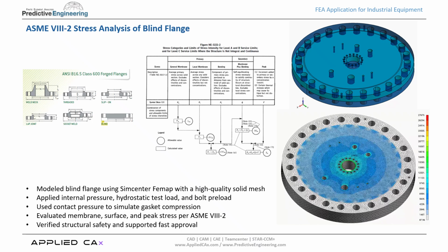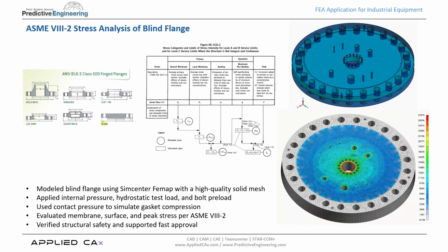We then compared membrane, surface, and peak stresses against ASME code limits. All results passed with satisfactory safety margins. This analysis gave the client confidence in the flange's reliability and helped streamline fabrication and code approval.